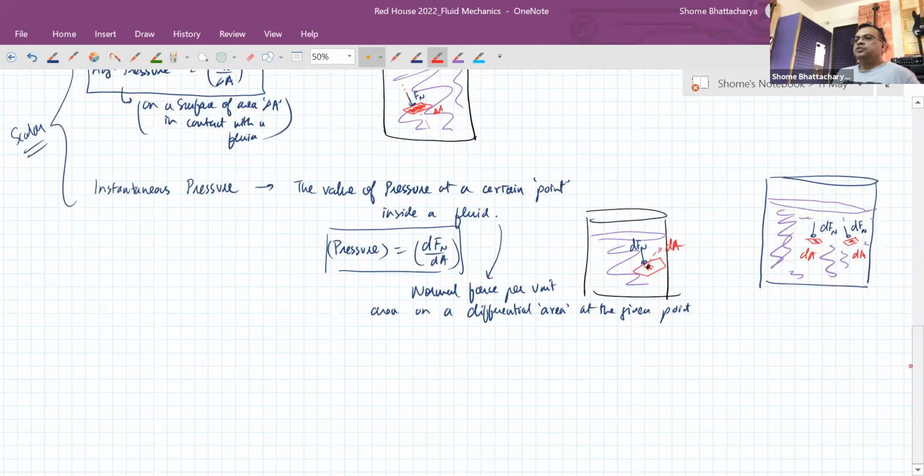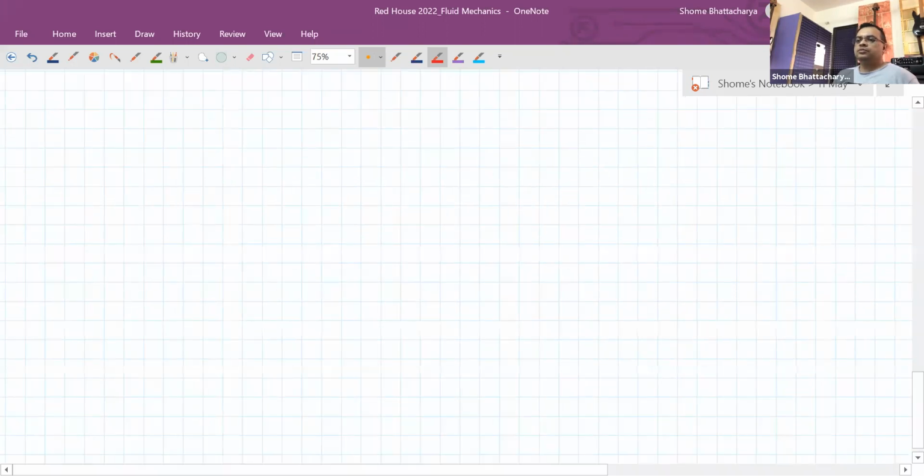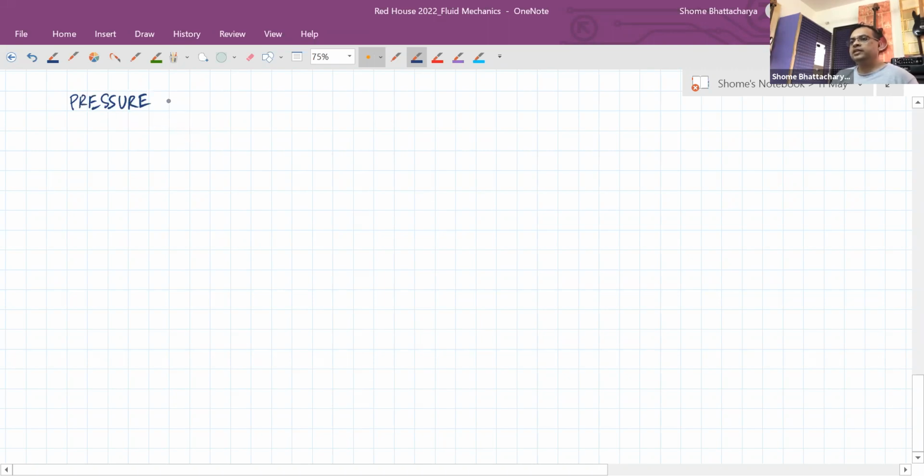Okay, so having understood about pressure, now we come to the very important first mathematical interpretation of pressure, and that is the concept of pressure gradient. All the properties from this point that we will see of an ideal fluid at rest, whether it is the buoyancy property or Pascal's law or whatever, we'll see it is related to what we are learning next, which is the concept of pressure gradient. We have seen the term gradient before in work energy, so it's in the same context.